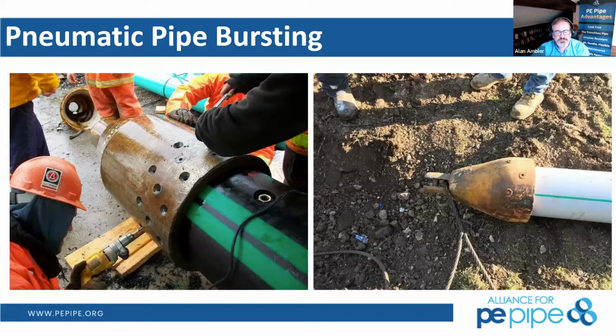It makes it easier for that closed circuit TV camera to capture images within that pipeline itself. Now, not having that carbon black within the pipe, we have limited time or lifespan above ground. We typically want to get it installed within a 2-year time period from manufacture.